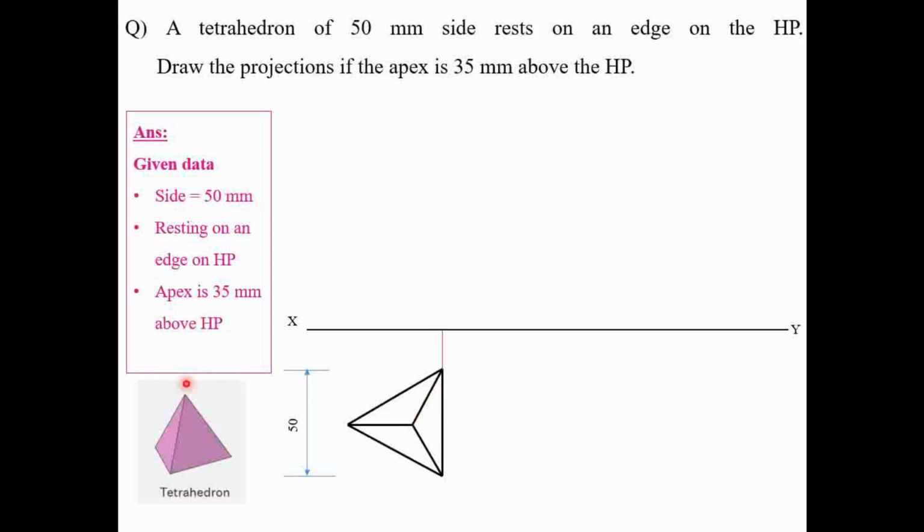When we observe it from the top view, the true shape of the base along with the visible edges also gets represented, that are nothing but the slant edges. Then the next step is we have to give the nomenclature. Top view without dash: ABC, the three corner points of the base, and the apex point is generally represented as O, and O to O is nothing but the axis which is present at the center of the object.